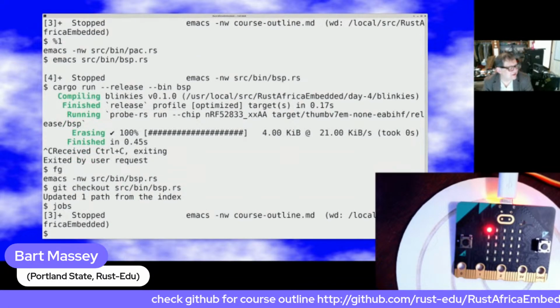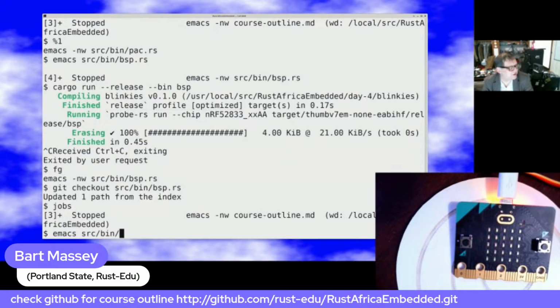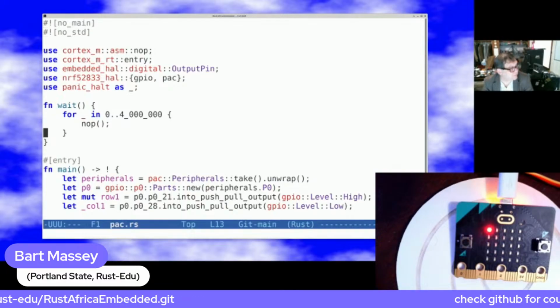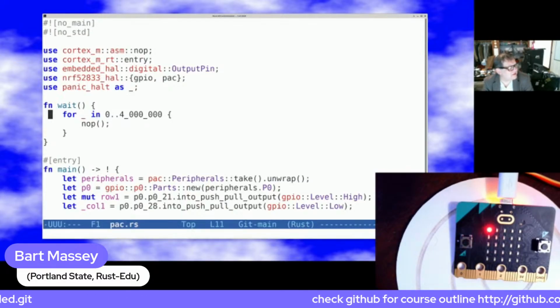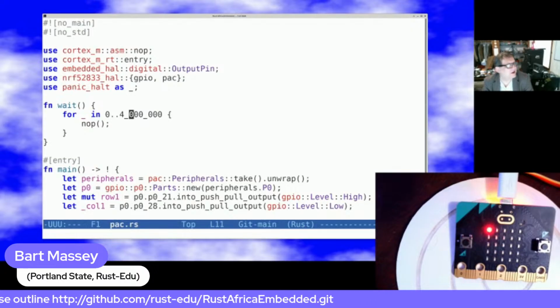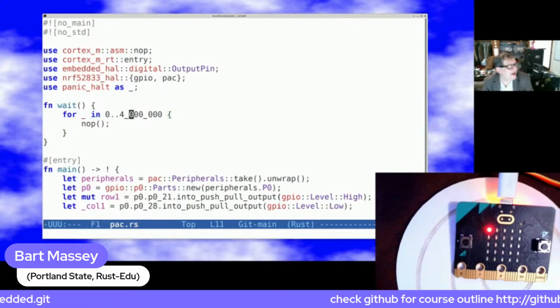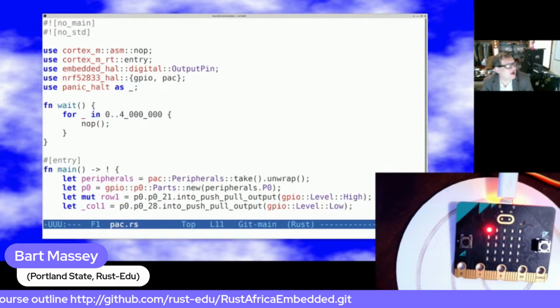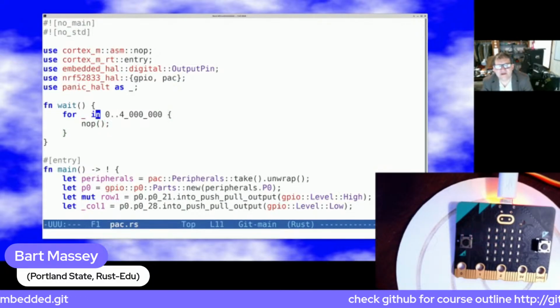There's a thing I want to emphasize about this spin loop stuff that I forgot to mention. Then we'll take a quick break. So again, the timing here matters, right? This thing is executing a machine instruction that keeps count of how many steps have gone. It's executing our no-op machine instruction, and then it's executing some instructions that go back and do it again. So we test, we increase our count, we check to see if the count is too big. If it's not, then we do our no-op, and then we jump back and do all that again. So this can be a lot of instructions.